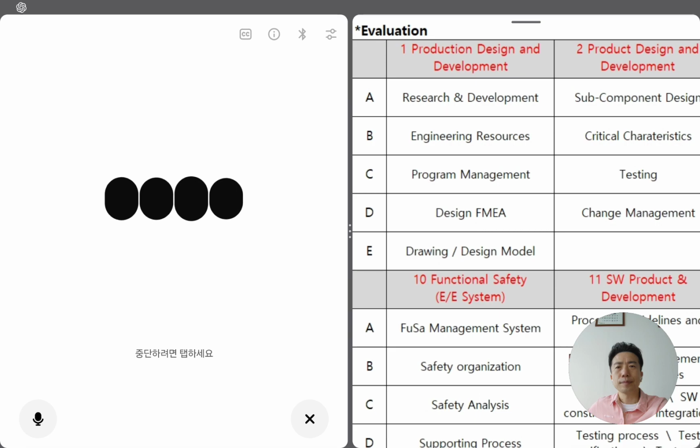To ensure potential failure modes are addressed, we use the DFMEA to identify risks and assign corrective actions. These actions are tracked until closure, and the results are reflected in design changes, test plans, or validation activities. Before finalizing the design, we confirm that all high-risk items have been mitigated and documented. This way, the DFMEA is not just a document, but an active tool to improve design robustness.